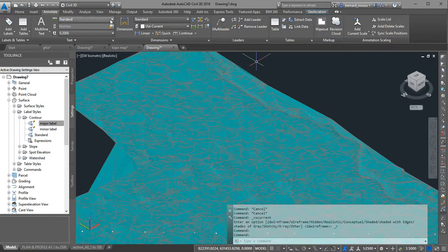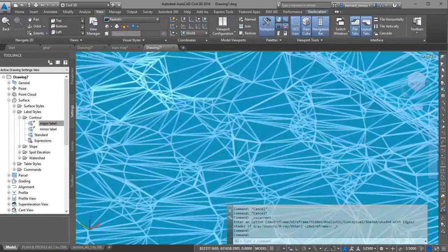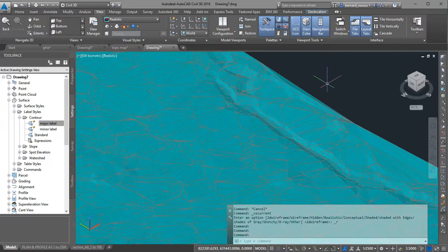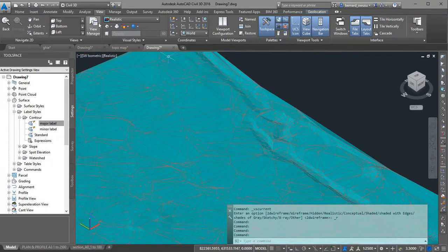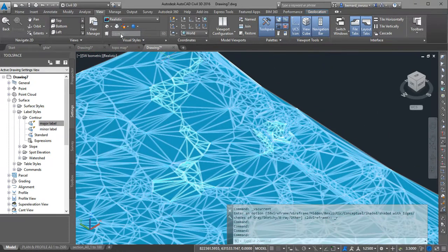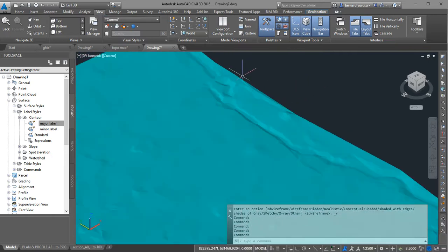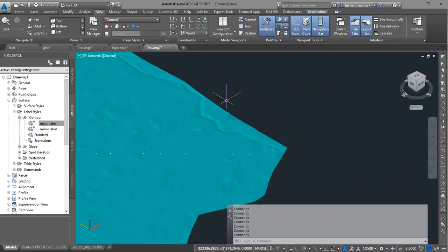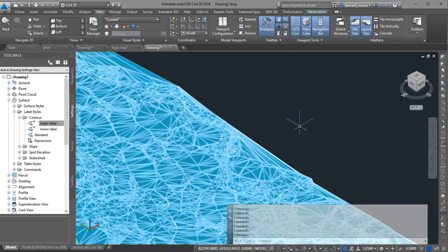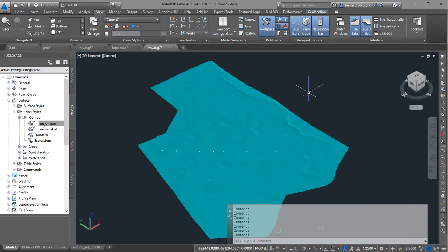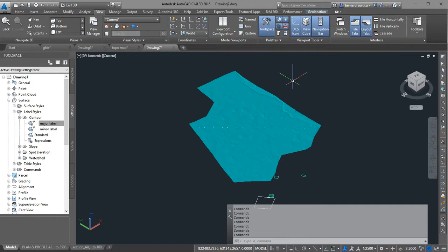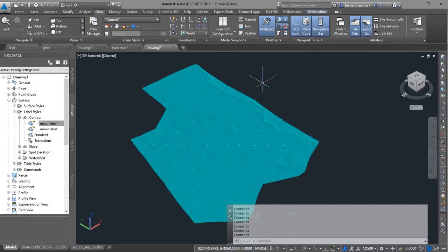And I said go to view so that we can turn off the lines. You see the lines are there. We want to turn the lines off. So you go to view, then you go to visual styles, then no edges. So you have this. So at least you have an idea. There's a channel here. So at least you have an idea that this is what is happening here. Please, are we okay? So this is where we got to. So let me